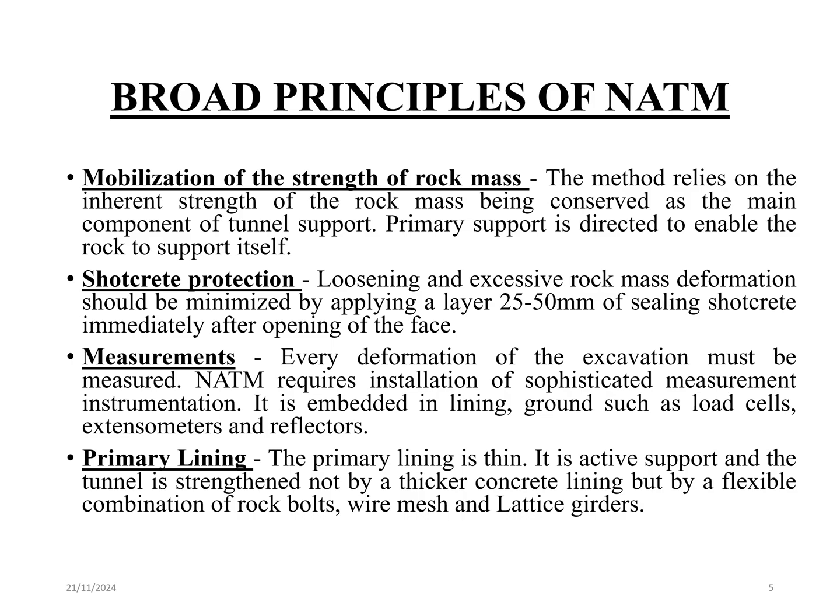In this, sophisticated measurement instruments are installed to monitor every deformation of the excavation. Last, the fourth one is primary lining. In this, a thin active support system using a flexible combination of rock bolts, wire mesh, and lattice girders is used.